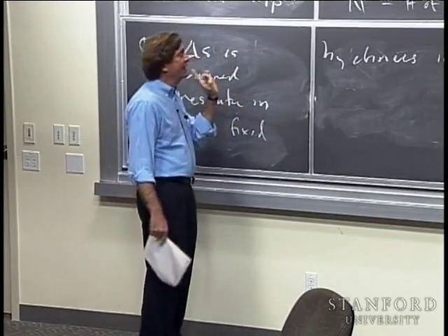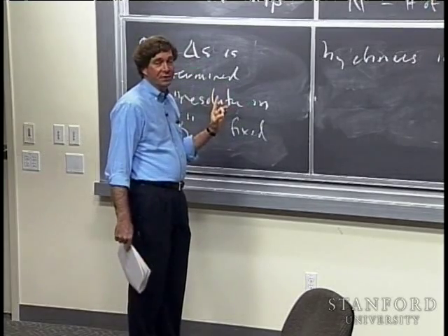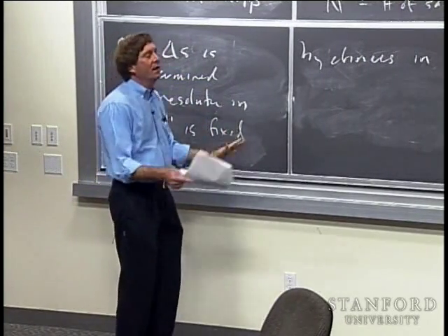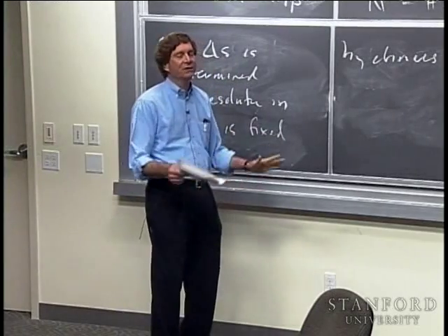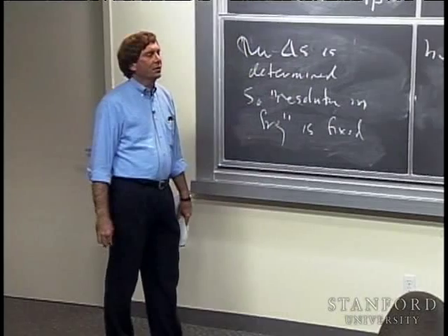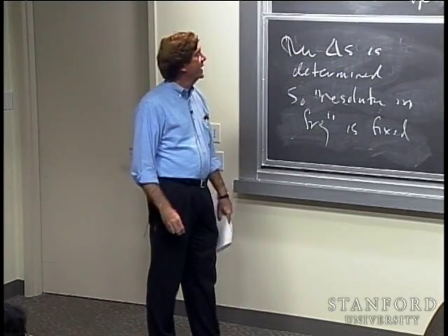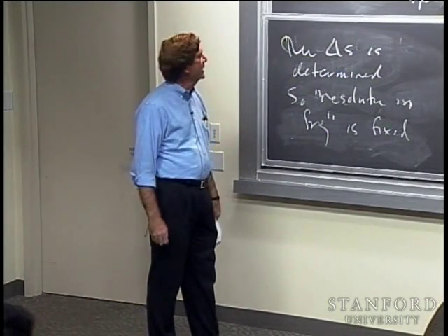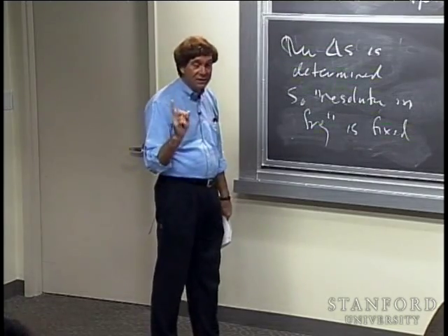And once you do that, then that determines what the resolution is like in the frequency domain. And there are ways of getting around this. There's zero padding, and not really getting around it, but ways of understanding it or massaging it. So-called zero padding, you have a problem on that, and you'll have other chances to experiment with that and other sorts of things. But it's built into the system, all right.